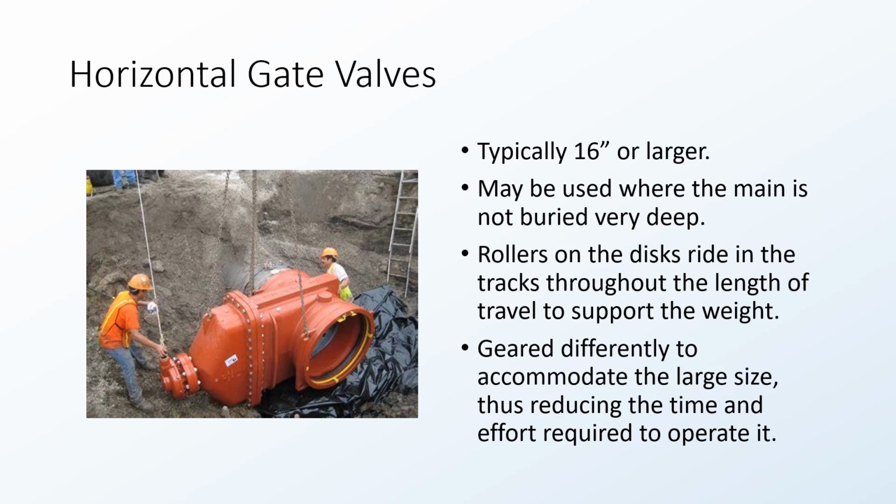Like it says here, typically 16-inch or larger, usually going to be installed on a main that is not very deep. Inside here, you're going to have rollers that help assist with the operation of this valve. Otherwise, you're just dealing with more friction and gravitational forces on this valve that will make it very hard to operate. And then they're going to be geared differently.